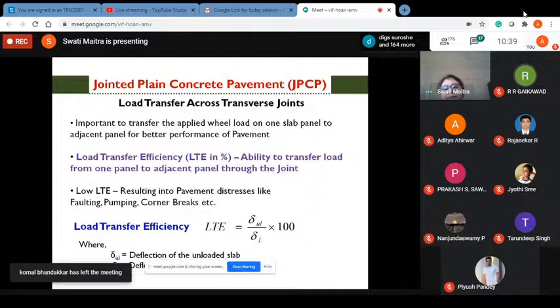In recent years, we have done analysis of concrete pavement using finite element modeling. This has been done by me only, and has been replicated on one national highway. You can see here that the concrete slab, 300 millimeter thick, has been modeled. Below is the 150 mm DLC, and below it is the 150 mm WMM layer with mixed macadam layer, and the foundation, which is assumed for the analysis as a Winkler foundation. It is represented by these spring elements, designated by these straight linear elements.